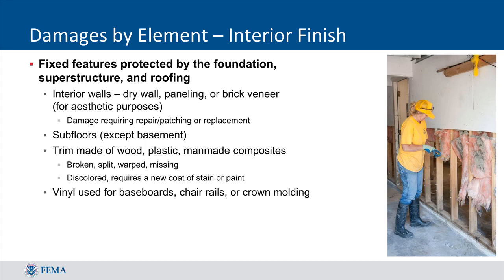Additionally, SDE does not evaluate damage to items like furniture, electronics, photos, or anything that is not considered a permanent feature of the structure. You may commonly run into damage where there is a need to repair or replace sections of drywall. This is especially true when floodwaters have caused damage above the first floor of the structure. Often, drywall can be cut and replaced in sections, so it is important to remember that just because there is some damage to a wall, the entire wall of drywall may not necessarily need to be replaced.